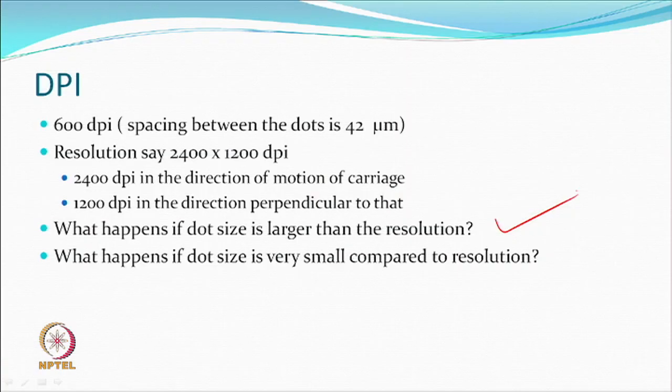Therefore, the drop volume is going to be controlled. If you control resolutions very large, the drop size cannot be the same as for a 600 by 600 or 600 by 400 dpi resolution. Drop size may be larger than a 2400 by 1200 dpi drop size, and so the volumes will have to be controlled in that.